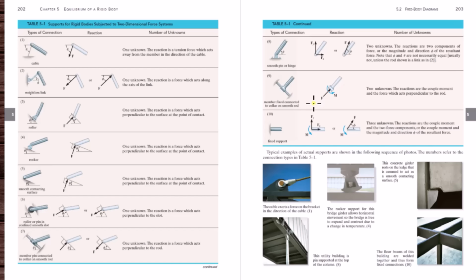In nature, forces and couple moments are applied to bodies. Moments about points are just an analysis technique to understand if the body is functioning the way you want it to function, right? Fixed supports resist translation in all directions and rotation in all directions. And remember, you can extend this to 3D easily. You just put an extra force in the z direction and two extra moments.